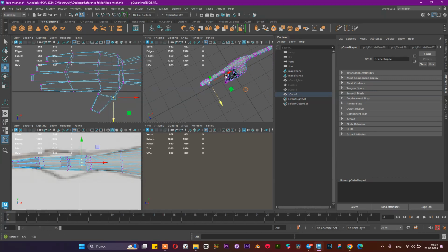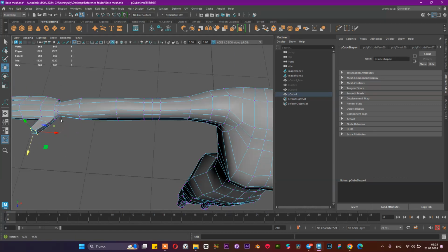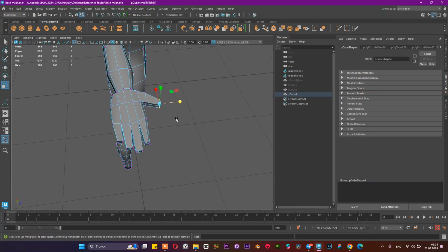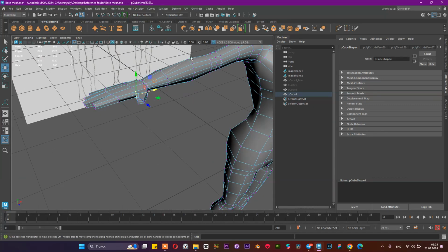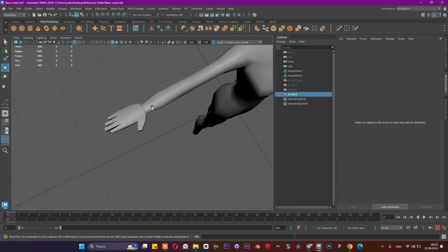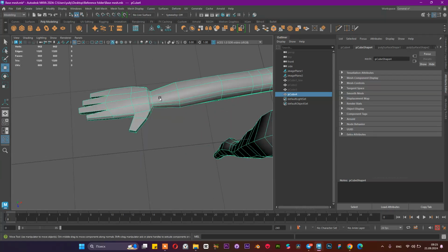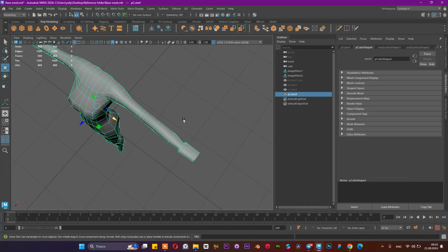And with moving these vertices, you can set it better. Maybe scale it down a little bit. Maybe move this entire group and make your arm bigger. It depends on your character. This is a basic and common structure for the hands. Later, we are going to add some more divisions here. We are going to add some in-betweens between your fingers. But this is for the low poly base mesh. And now I'm going to soften the edges here. And I'm going to create another copy, another side of this hand.